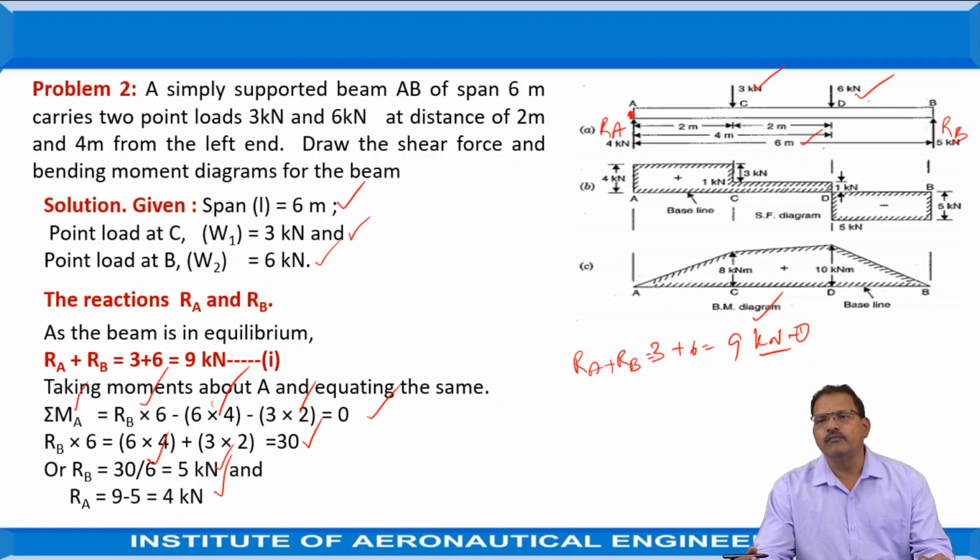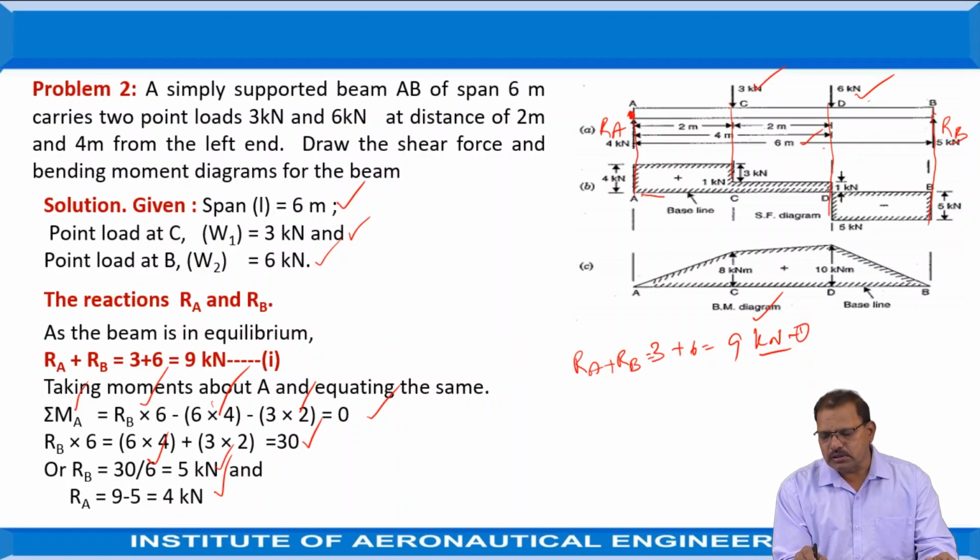So after determining the forces at A, B, C and D, draw the shear force diagram. In order to draw the shear force diagram, first draw the beam as per a suitable scale. Draw the vertical lines in the downward direction from the various points where the forces are acting. At a suitable distance, draw a horizontal line to represent the length of the beam.